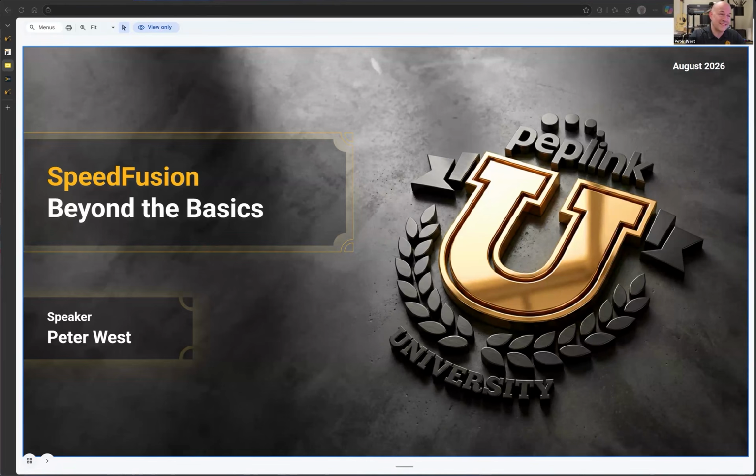Adaptive uses between 6 and 20% overhead on top of bonding overhead. So I'm using 18%, and then I add forward error correction, which adds bits into the program, which is going to add overhead to that at 6 to 20%. Low, FEC low is 13%, and FEC high is 26%. And so once again, those are additive calculations.